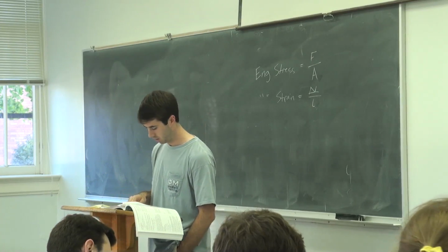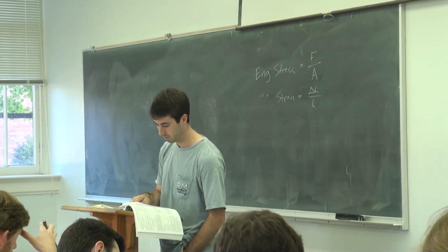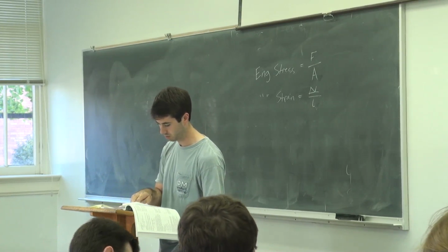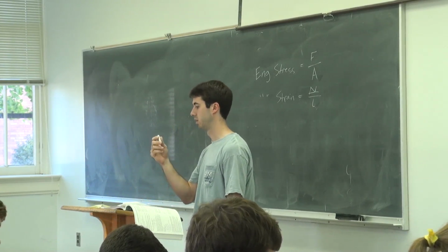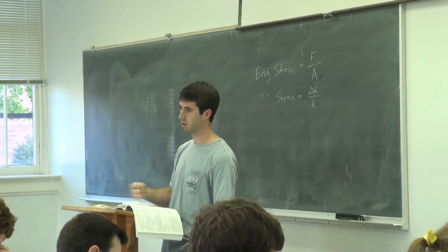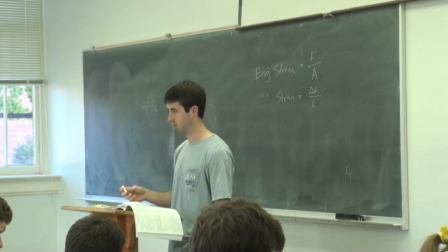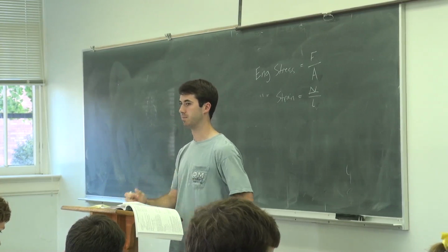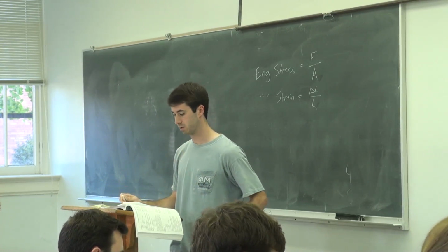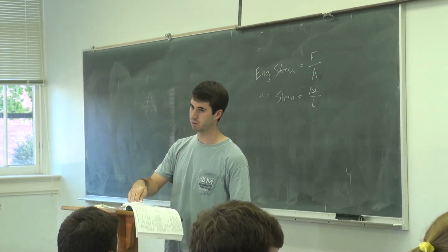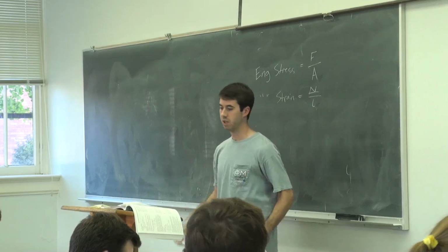When you get into the yielding phase, as you can see on this diagram, you're straining more and more. You're getting further and further to the right, but you're not increasing stress. During this stage, it's just plastic deformation, I guess, where the particles themselves are realigning and shifting so that it's just stretching without adding anything else. And then you go into the strain hardening zone, where now everything's kind of reset itself, and you start taking on stress again.